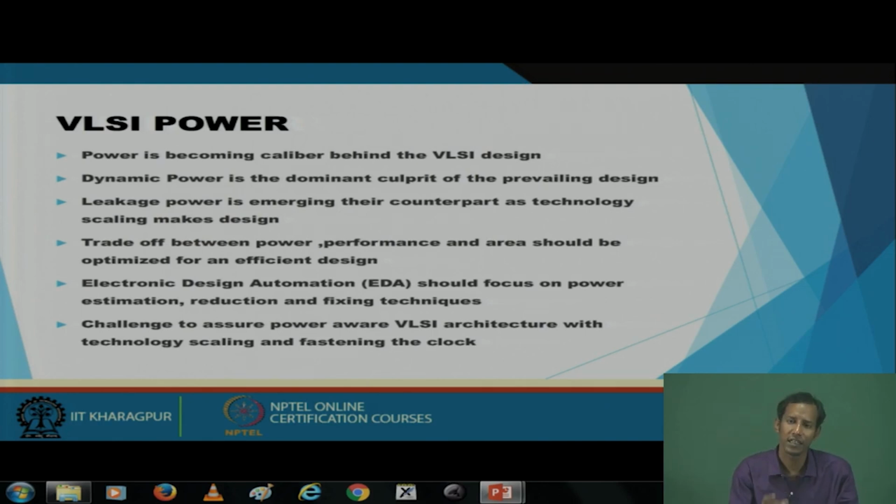In timing also they can apply static timing analysis, which we have seen. Manually I can calculate, but if there are millions of paths, handcrafted calculation of each of these paths is not at all possible. If the tool does the static timing analysis, it takes each of these paths, computes the timing analysis for each, and shows you a report. If any of your timing constraints are violated, it will immediately report that this particular path is violating. So both area optimization and timing optimization have been done automatically using the EDA tool.